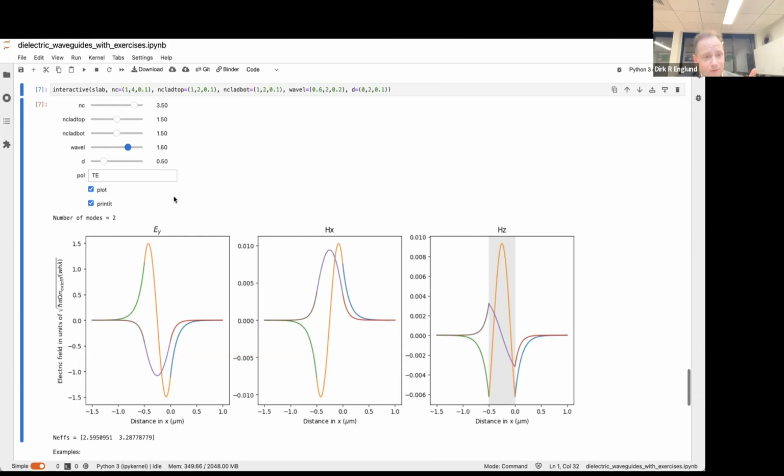Well, sometimes it's useful to have multi-mode operation in a waveguide, so more than one TE waveguided mode. But you have to be very careful because the two fields can couple in a way that you don't know in advance, because it's difficult to fabricate something exactly to nanometer precision to your specification. So you generally wouldn't know what the coupling rate is between these modes and what the dispersion is between the modes. So generally people want to work in a single mode configuration.